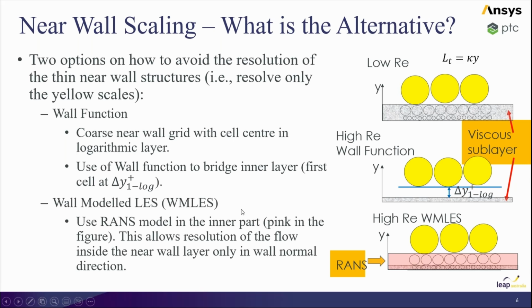So the other option is to do modeling in here. And so we know from all the derivation of the RANS models that where they're really good is in the boundary layer, especially the SST model, which has been tuned for that. So SST is going to do a really good job. If it comes to an adverse pressure gradient, it's going to want to separate, and it's been tuned to do that, where the log law will just carry on sticking the flow to the wall. So we can see there's a big advantage, if we could, of using an appropriate model in the two different domains.